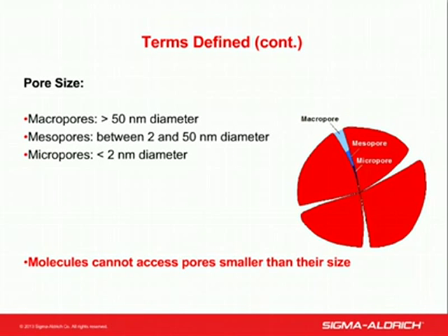At times there are things that complicate matters, or the molecules of interest have different shapes and sizes on their own. For example, the freons with a large chlorine atom are in a gas phase at room temperature, but oftentimes we can retain them using a weaker adsorbent such as one of the Carbopacks. So using a multi-bed tube that contains different types of adsorbents will always allow us to collect a broader range of compounds from a single tube.